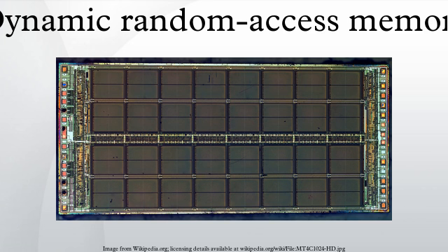It is technically DRAM, but behaves much like SRAM. It is used in Nintendo GameCube and Wii consoles. Reduced latency DRAM. Reduced latency DRAM is a high-performance double data rate SDRAM that combines fast, random access with high bandwidth, mainly intended for networking and caching applications.